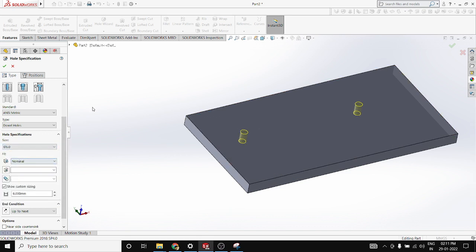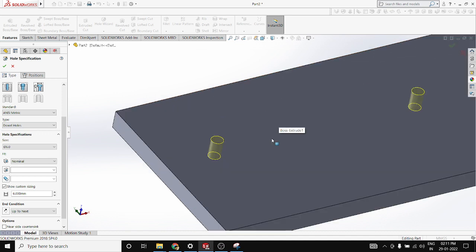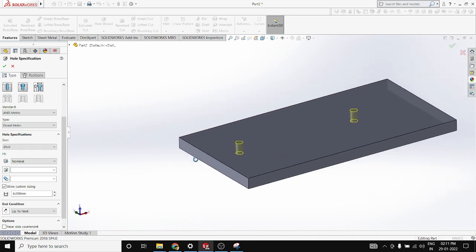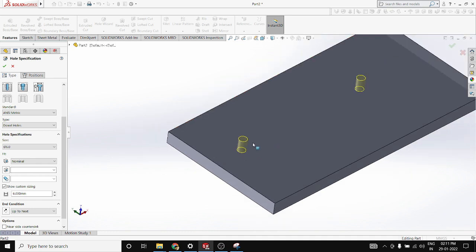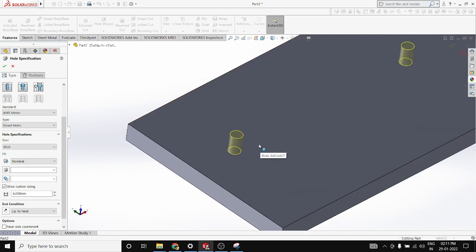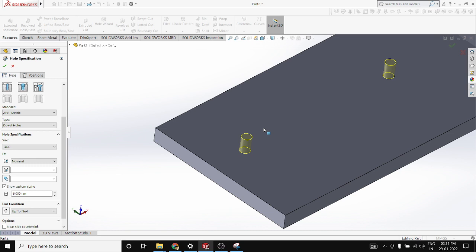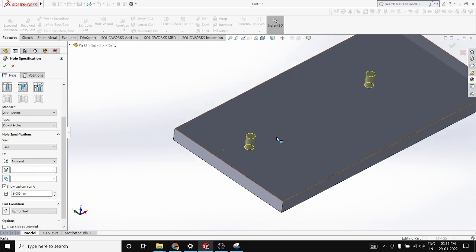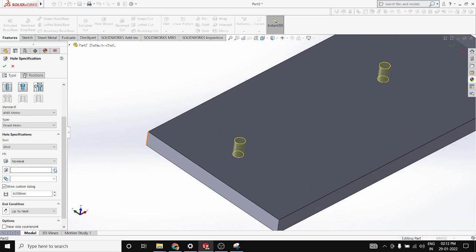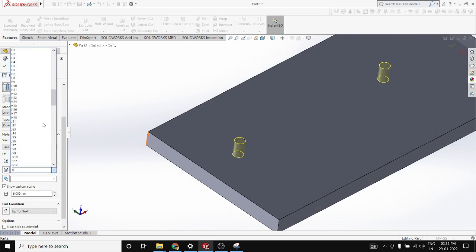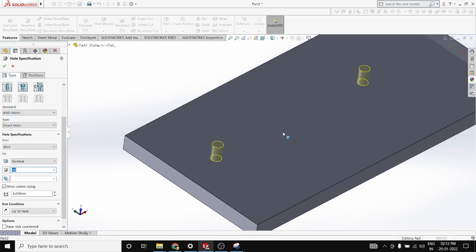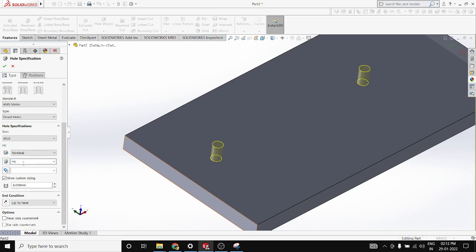Then in the dowel hole, we have to apply some tolerance while doing projects. Some person will do the 3D, then some other person will do the 2D. So he might not know the purpose of the hole, and he doesn't know that value. So my suggestion is always try to apply tolerance at the hole level. Somewhere we are using H6, F7 based on the mating function. You can apply H6 here, that means the tolerance. You can apply the tolerance in the fit command.